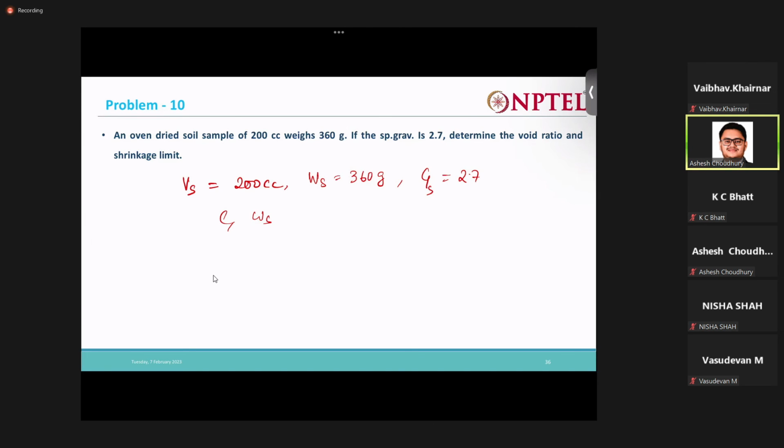What is the dry density of the soil? You can calculate, right? Dry density is nothing but dried weight by dried volume. Sorry, one second, not volume of solids. The dried volume won't be just the solids, because air will also be there, right? So it will not be Vs, it is Vd. In Vd you have both the volume of soil solids and also the volume of air.